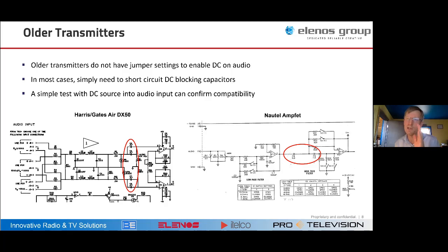When I say large, I just mean it's larger than any of the subcarriers. It maybe represents, don't quote me, 10 or 15% of your total power, unlike AM, where it would be, let's say, 80% of your total power. So it's large in that it's bigger than the other subcarriers, but it's not as big as it is with analog.